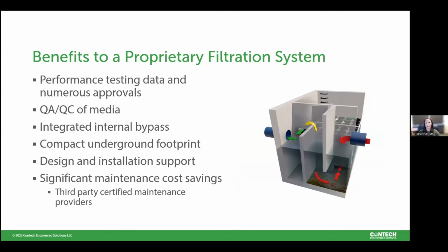What are the benefits of using a proprietary filtration system like a media or membrane system versus a conventional? Vaco touched on it earlier and explained it very well. Their proprietary BMPs, best management practices, are held to a high standard. They have to go through quite a bit of testing in order to get their approvals, and that data has been repeatable and proven. With conventional systems, there are plenty of studies out there you can reference, but they don't have to go through that same approval process as proprietary systems do.